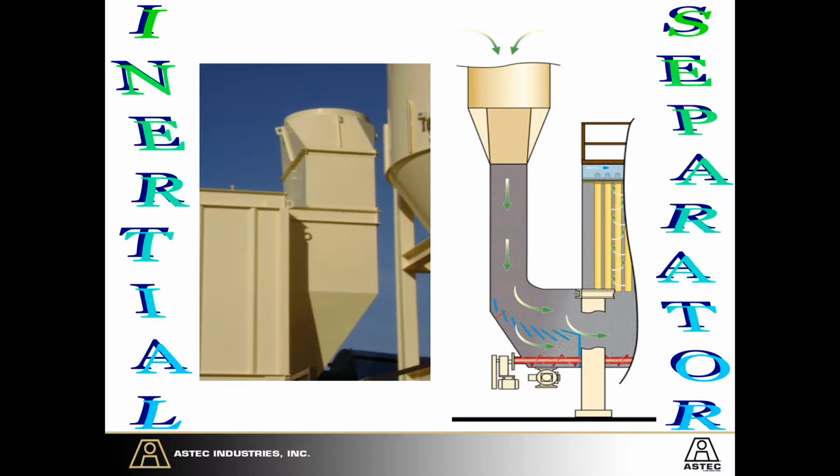The new design, or what we're mostly seeing now on plants, is called an inertial separator. It's more of an elaborate word for an elbow. As you pull exhaust from the drum, as it moves down this high velocity air, the heavy materials hit these louvers and they fall straight down into the auger. And then you're conveying most of your minus 100s there straight back over to the drum. Then the lighter dust, the minus 200, gets conveyed over into the baghouse. And we've got some illustrations we'll show you a much better representation of what we got here.